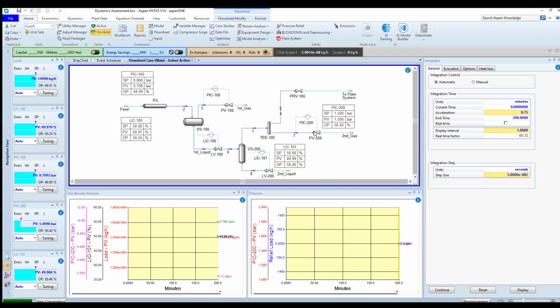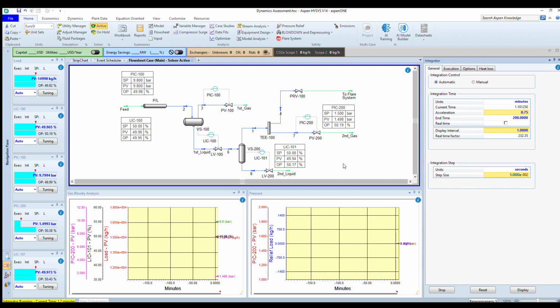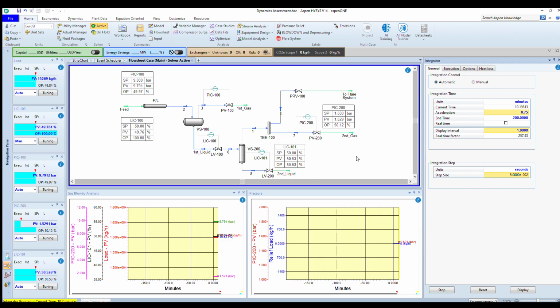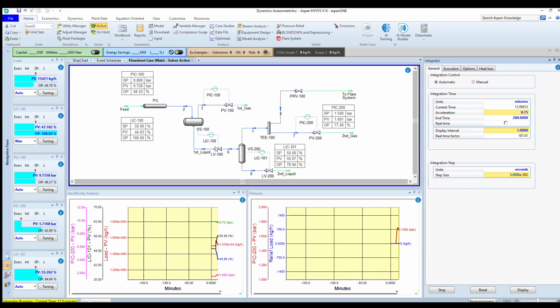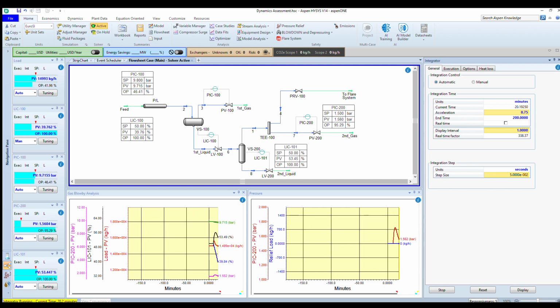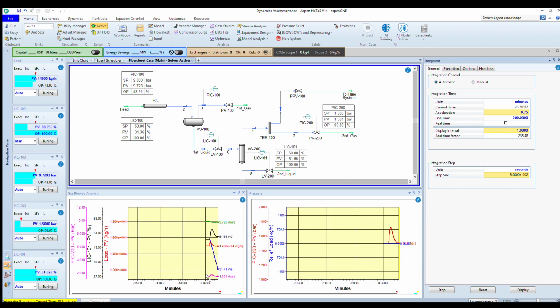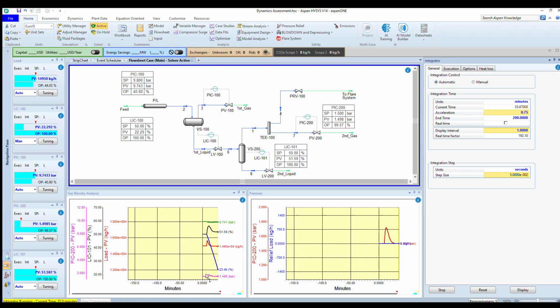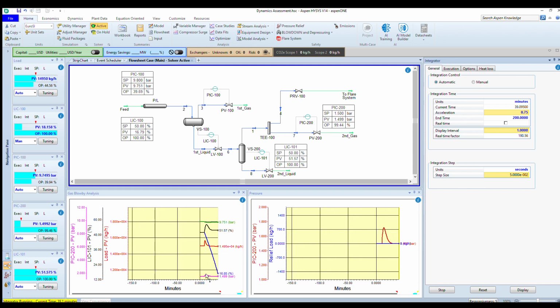All these things will lessen the relief load and relief demand on the LP interface, and that was a recommendation from API 521. So now the simulation is running, and in a few minutes now, as I can see, this has become 100% full open. I can see a marginal increase in transient pressure at the LP interface.